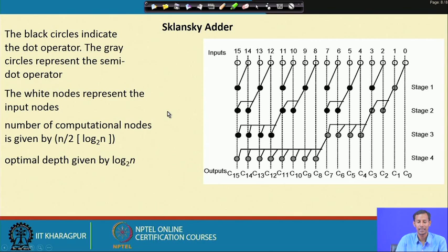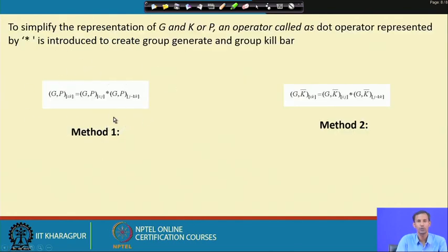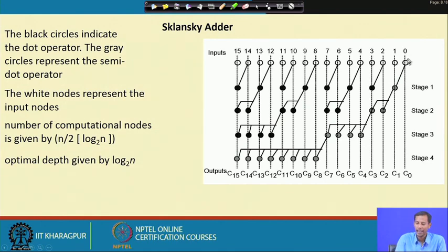So, based on this, what we are doing is pre-computing the prefix, and that is represented by one node. Now, we will follow one regular structure to compute the sum and carry value for each bit position. Okay. So, how can we do that? Suppose I have 16 bit inputs, that is, I require a 16 bit addition. So, this white color box is nothing but the DFG of this parallel prefix adder, which is known as the Sklansky adder.